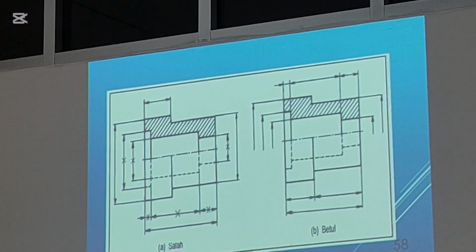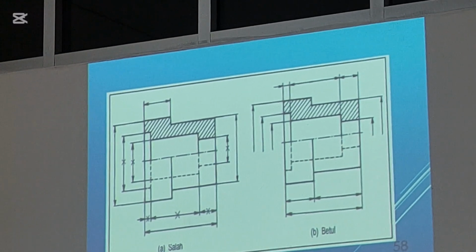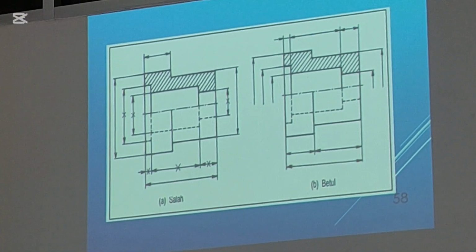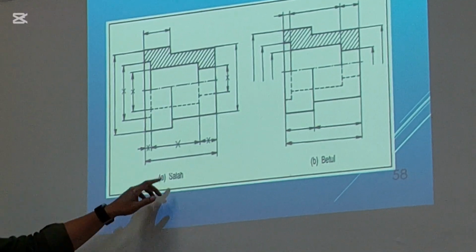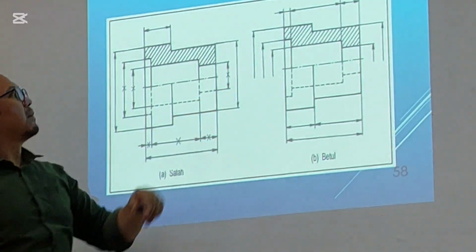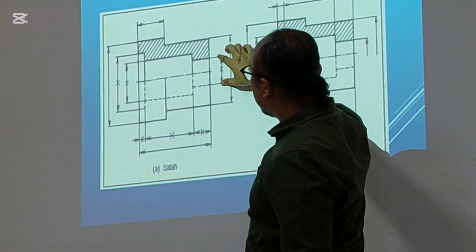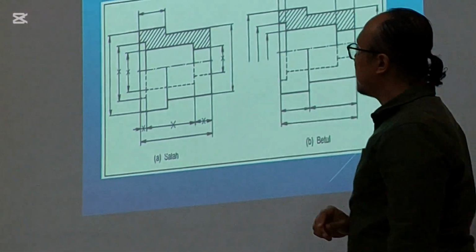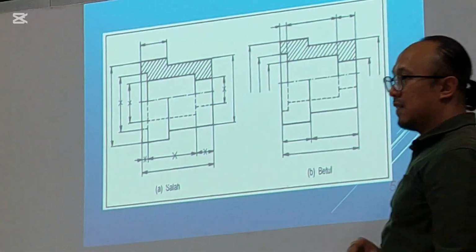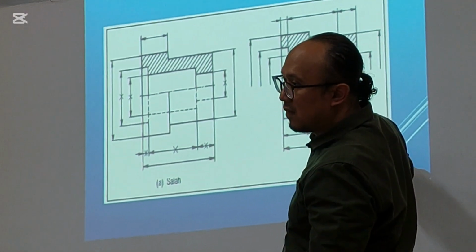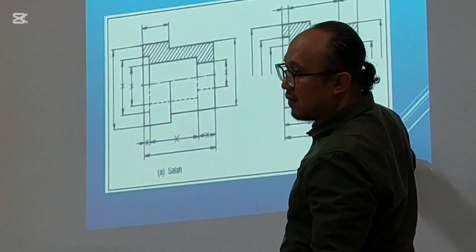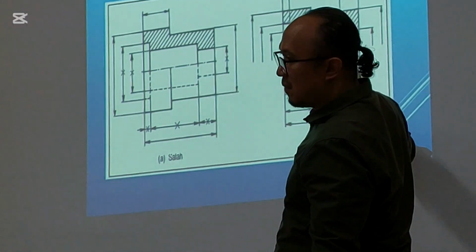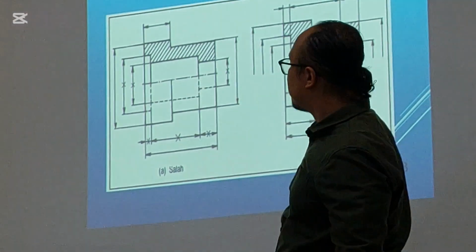Yeah, like the X on the middle of the arrow instead of not making it from the X. This one? Yeah. What happened with this one? Also, the dimension line is aligned with the object and then the helping line. Is it? Yeah, it's not an object line. Yeah, right.